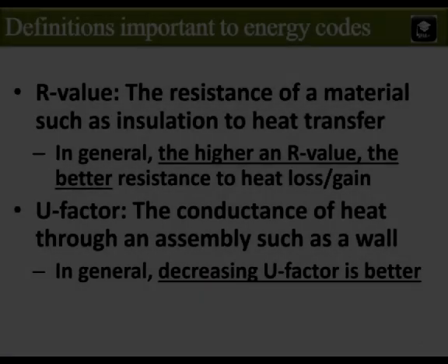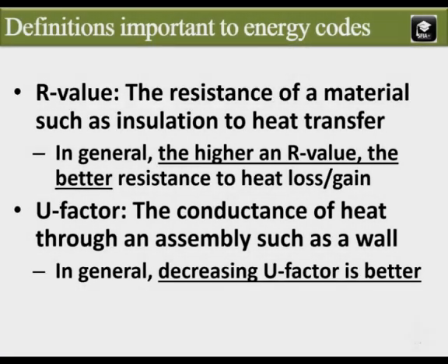There are some basic yet important terms that describe the thermal performance of insulation versus an entire assembly. Both the term R-value and U-factor will come up throughout the presentation today. The R-value describes the ability of insulation or a material to resist heat flow. A higher R-value is better than a lower one.